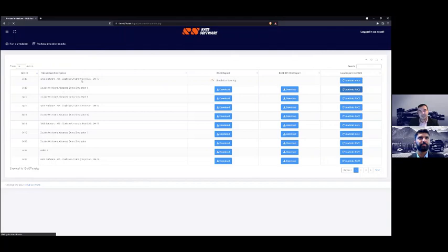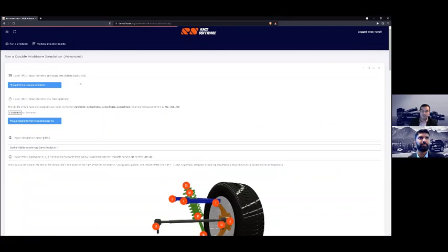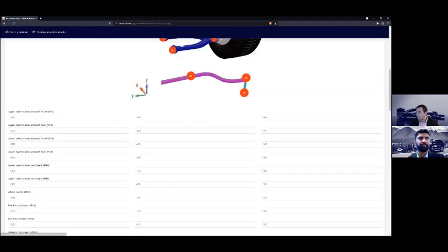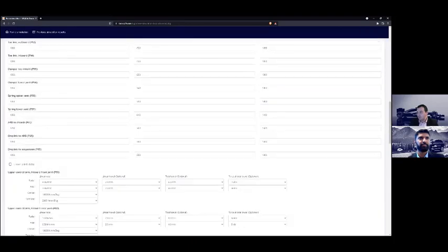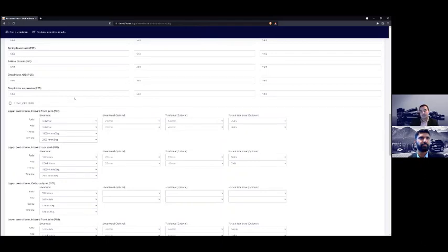As mentioned, in the advanced template you also have the anti-roll bar, the roll motion test, but you can also specify each bush and it's all 6 degrees of freedom. Again, you have your XYZ coordinates, and after that you can specify your bush stiffness. So you specify your initial linear weight, for how long the linear weight is applied to, the total travel, and the force at the total travel. These are the parameters which you are going to use in order to generate your non-linear splines for each bush.